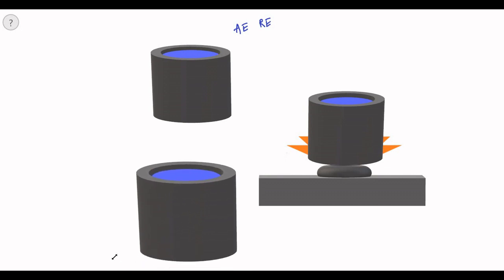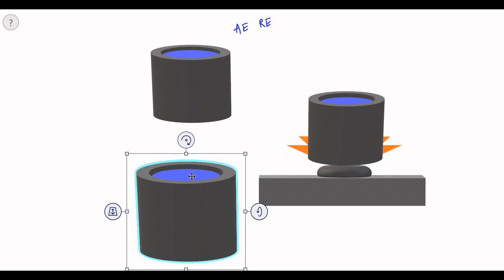So in that case, if we only take the volume of the liquid into consideration, that will give us the wrong result, an error, because the change in volume of the container also affects the measurement of the increase in volume of the liquid. There will be an error, because the container is also expanding along with it.